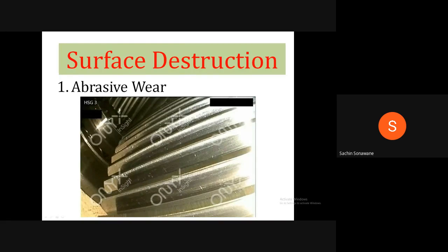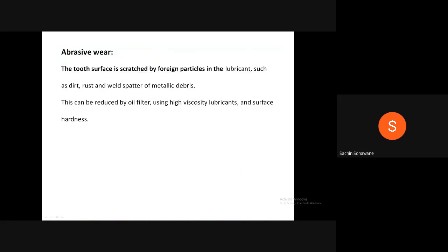Therefore, the tooth surface is scratched by foreign particles in the lubricant such as dirt, rust, and weld spatter, metallic bodies or debris. This can be reduced by oil filters, using high viscosity lubricants, and surface hardness.